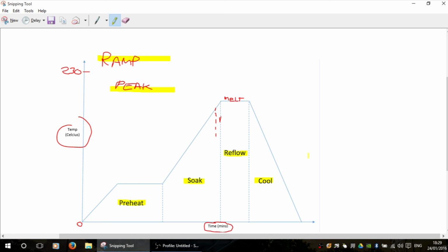The peak temperature, of course, is important. Lead-free solder is melting at 217 degrees Celsius and leaded at around 145 to 165 Celsius. So make sure your peak temperature is set accordingly. Cooling, of course, remember, good rule of thumb is to come down between 1 and 2 degrees per second to around the 100 degrees Celsius mark, and then add any induced cooling from the machine to get it down to room temperature. And remember that these different types of BGA will need their own unique profiles setting up, so ensure that you do that to make sure that you get a successful process.